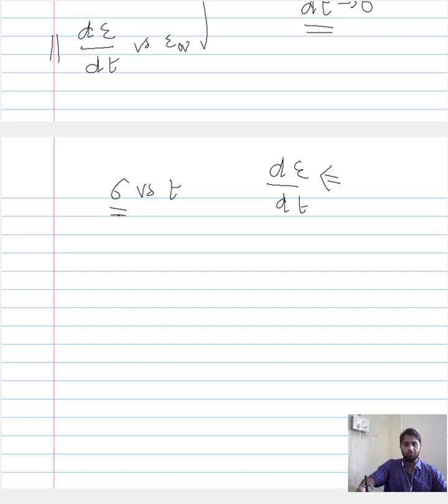So instead of plotting strain along the y-axis, one way of introducing a new representation of the creep curve is by considering a condition wherein the creep rate is assumed to be constant, and the mechanical condition that is required to keep this creep rate constant is plotted with respect to time. And of course, you can also replace the time here with the overall strain exhibited by the material, and this again would provide a plot wherein instead of objectively talking about change with respect to time, we can subjectively talk in terms of the behavior of the material, the stress and the behavior of the material.